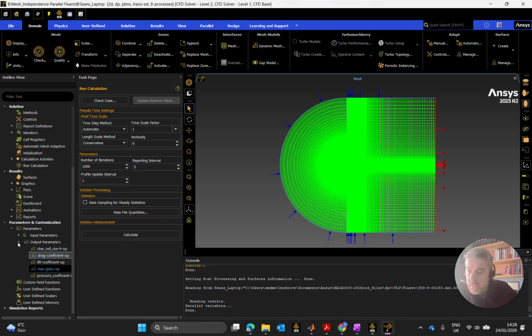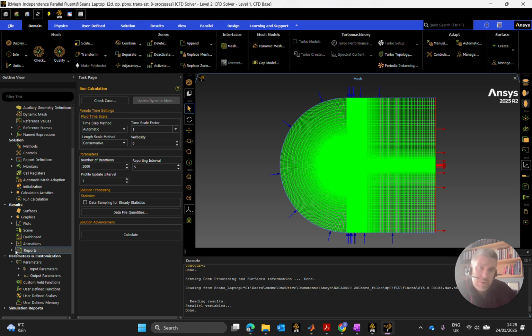Okay, so how do you get rid of these input parameters? You don't have to, you can leave all these there, but you're just filtering through more data. And as it happens, the way I take the data off of ANSYS, I usually execute and solve and process the data in MATLAB. And the fewer columns you need to extract and filter your way through in an Excel sheet that's exported off the design table, the easier and the faster it gets.